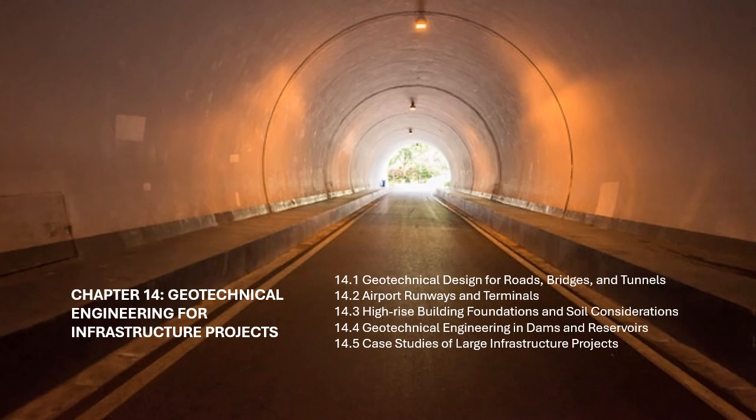Geotechnical considerations. For arch dams, the rock quality and stability at the site are critical. The rock must be strong and resistant to cracking under pressure, and the dam's design must account for rock mass heterogeneity. Site investigations and rock mechanics analyses are crucial for ensuring the foundation's integrity.